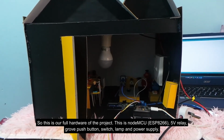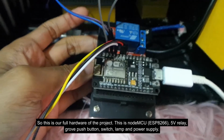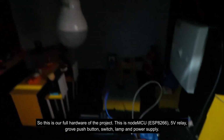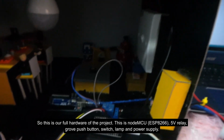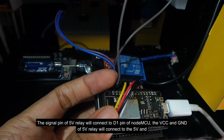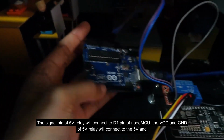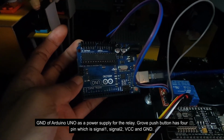So this is our full hardware, and this is NodeMCU ESP8266, 5-volt relay, group push button, switch, lamp, and power supply. The signal pin of 5-volt relay will connect to the D1 of NodeMCU. VCC and ground of 5-volt relay will connect to the 5-volt and ground of Arduino Uno as a power supply for the relay.